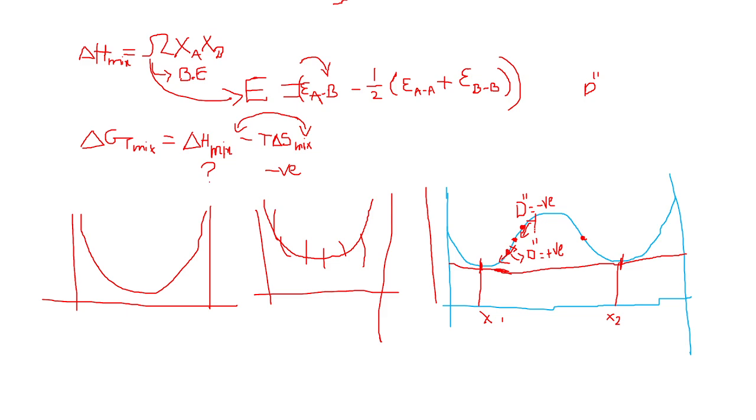That means the free energy change is so large, which is again a negative value, a decrease in negative value. The whole system has enough energy. It can just bypass the nucleation part. It can just form a different phase. How does it form? It forms by the migration of atoms across the boundary. So that's how you end up with two different phases.